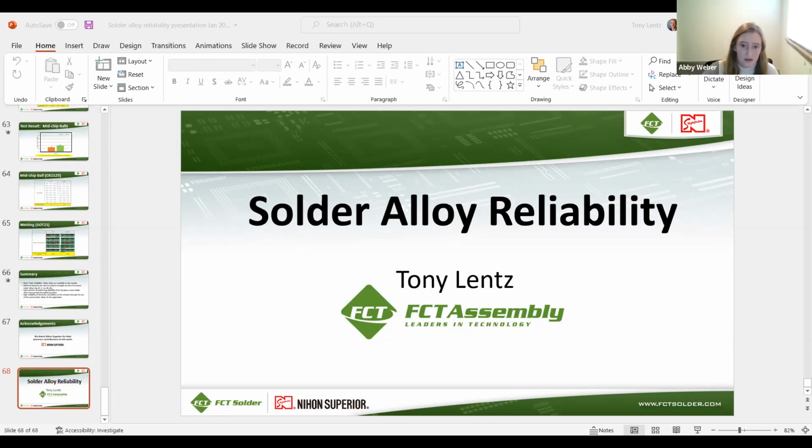Does LFC2 require a special reflow profile control compared with SAC 305? No, actually LFC2 can reflow in a typical SAC 305 profile, or, like I mentioned, because it has a slightly lower melting point, it can reflow with roughly a 5-degree lower peak temp than SAC 305.